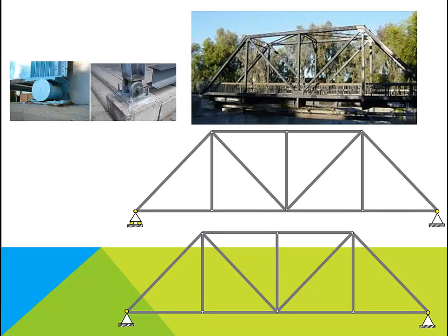If we put one support as a roller and one as a pin for a bridge, during the thermal expansion in daytime and contraction at nighttime, the bridge can expand or contract without imposing any stress on its members.